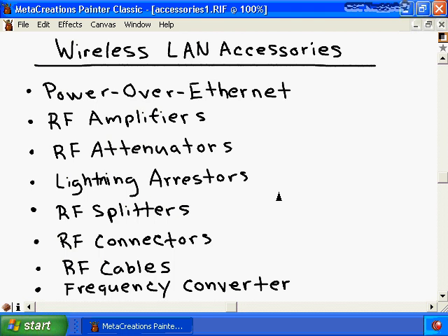We have standard connectors, and then we have non-standard or proprietary connectors, and those connectors have the prefix of RP for reverse polarity. And remember that we have two general types of cables. We have our RF cabling, and then we have the pigtail adapter cabling, which allows us to have two different types of connectors, so we can adapt to standard, to non-standard, or proprietary devices.